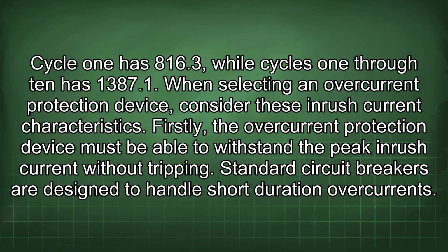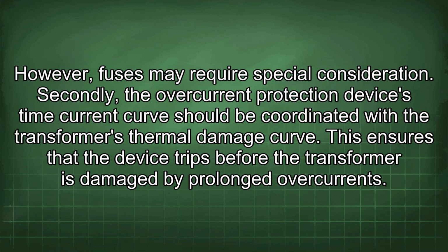When selecting an overcurrent protection device, consider these inrush current characteristics. Firstly, the overcurrent protection device must be able to withstand the peak inrush current without tripping. Standard circuit breakers are designed to handle short-duration overcurrents. However, fuses may require special consideration.